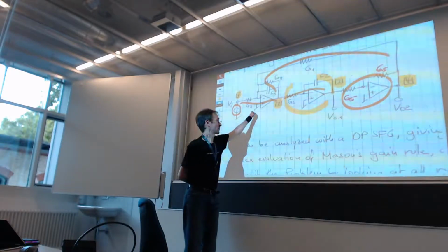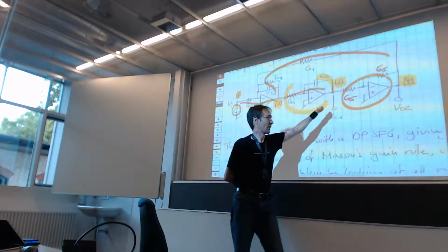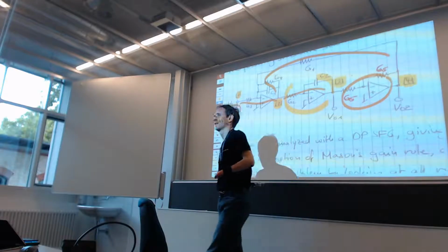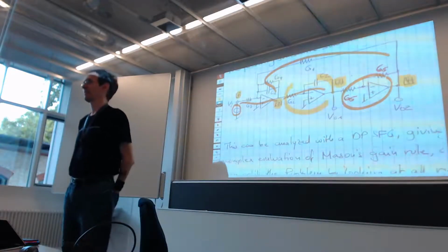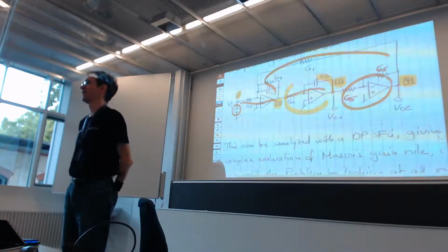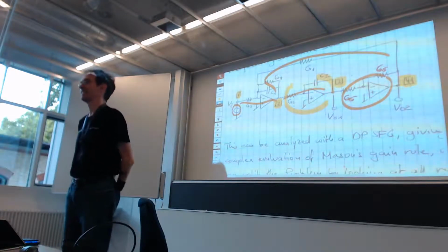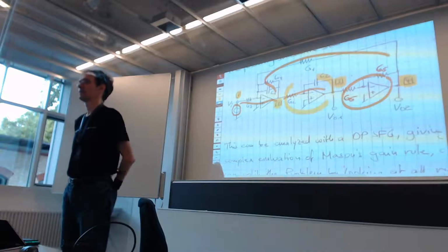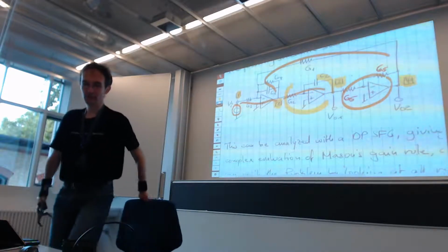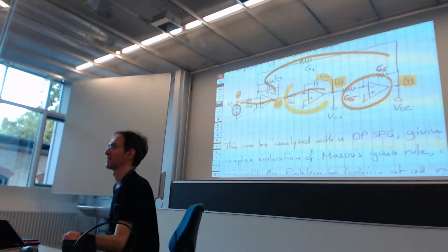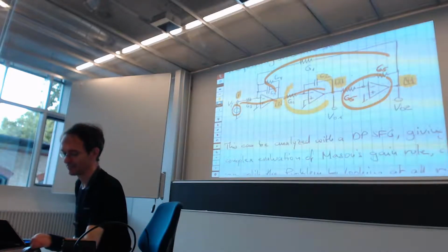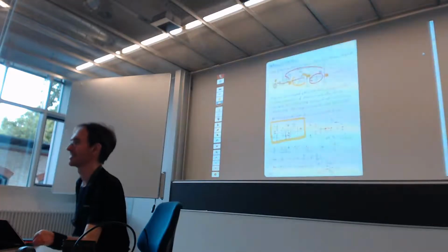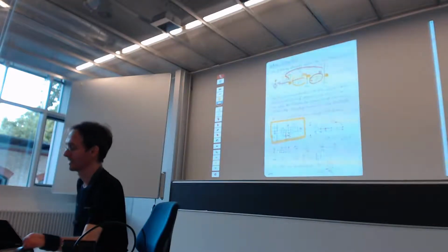Here, all of the amplifier inputs are virtual grounds. So at the negative input of these amplifiers, there will be very little variation of voltage. Therefore, they will be very linear. So if you do it like this, you will get the linear filter, which can also give you a good linearity behavior. So not much distortion, if you already know what that is. If you don't, wait for lecture number 6.